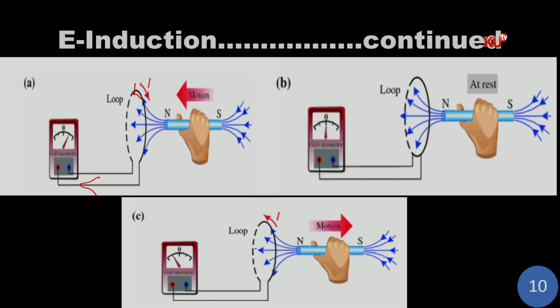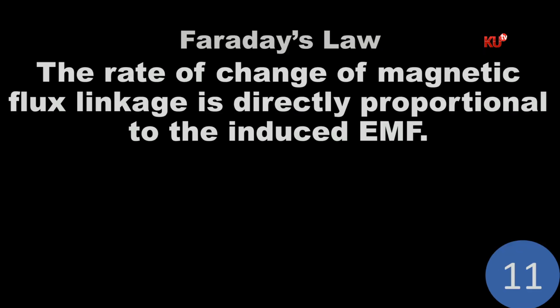And so this face adjusts itself to acquire the south polarity, which resists the cylindrical magnet from being pulled away. And so charges displace anticlockwise, current flows clockwise, such that we have current in the circuit moving in that direction. And so the pointer deflects to the left of the center.